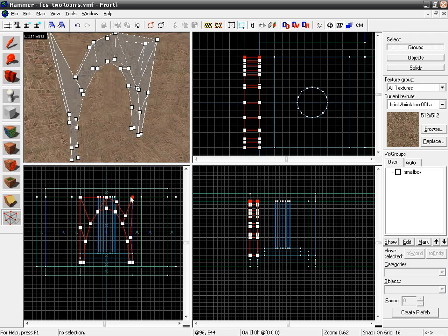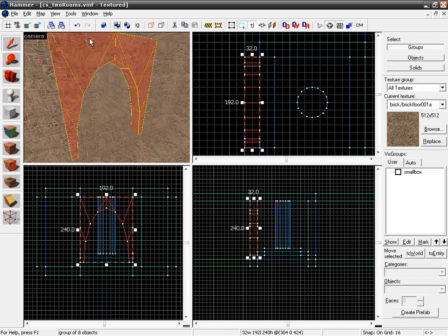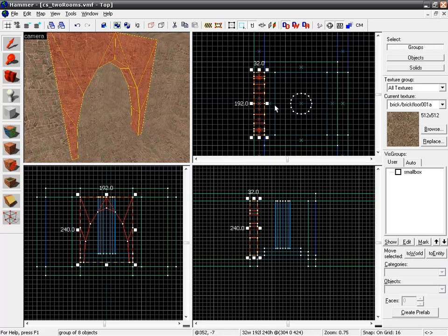At this point at the top, drag the side up just a couple units. And it doesn't actually complete until we change tools. So we'll have to change to any other tool. Let's go to the selection tool. And you see now we have a solid object in the fewest number of pieces possible, filling that space. And now we have it finished.